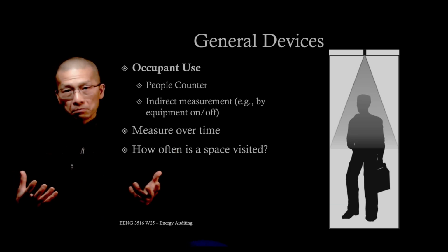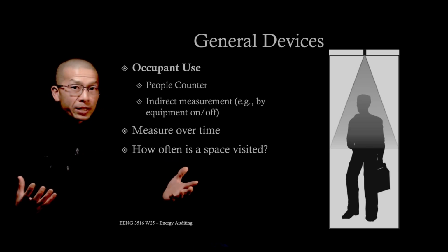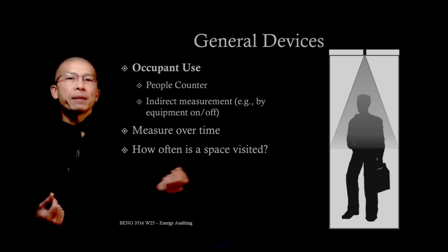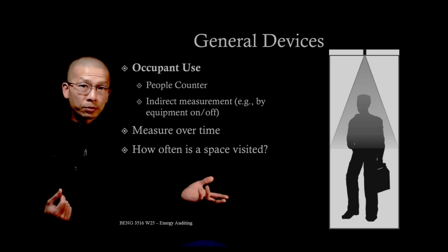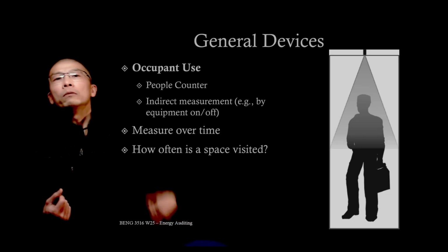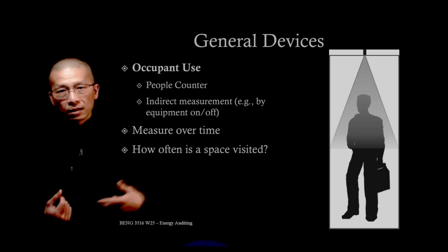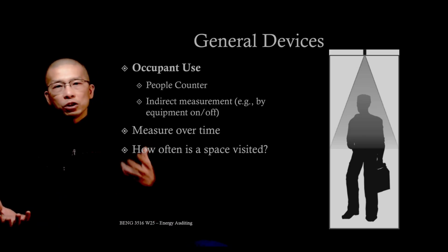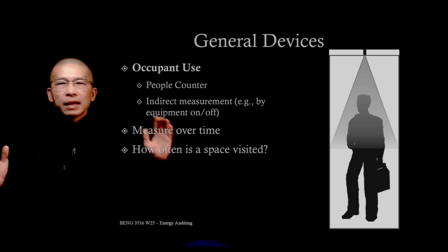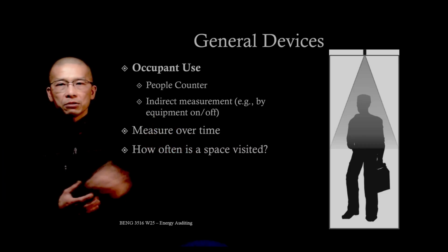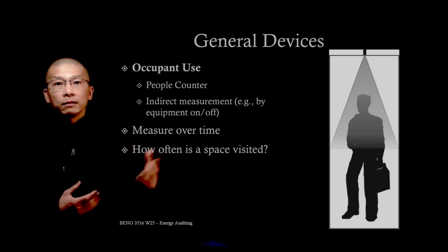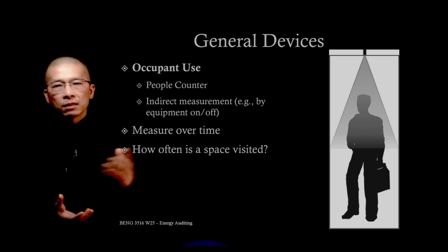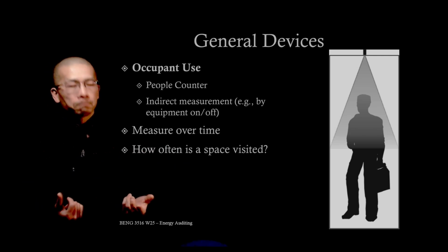Well, using the people counter data, we can justify what's called demand controlled ventilation, for example, DCV. More people, more ventilation. Less people, less ventilation. If the sensor shows the gym is empty 80% of the time, you can recommend slowing down the fan to save thousands in heating and cooling costs.